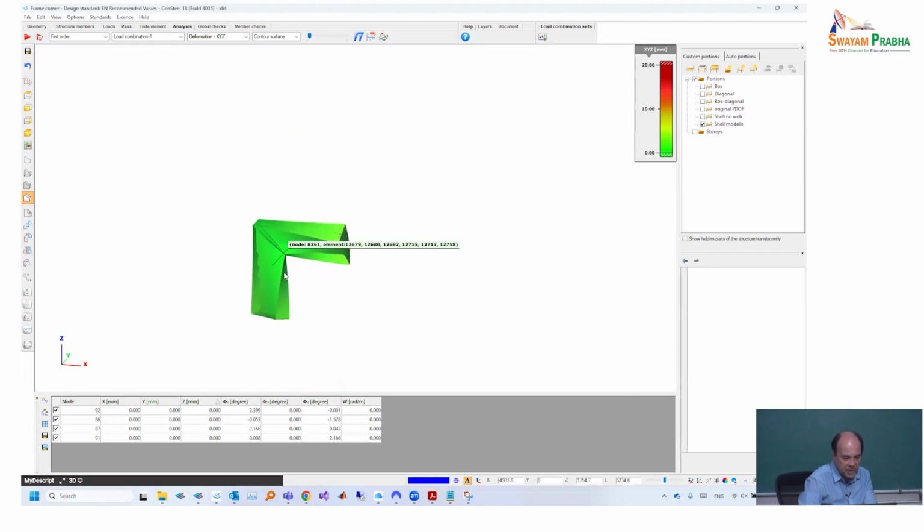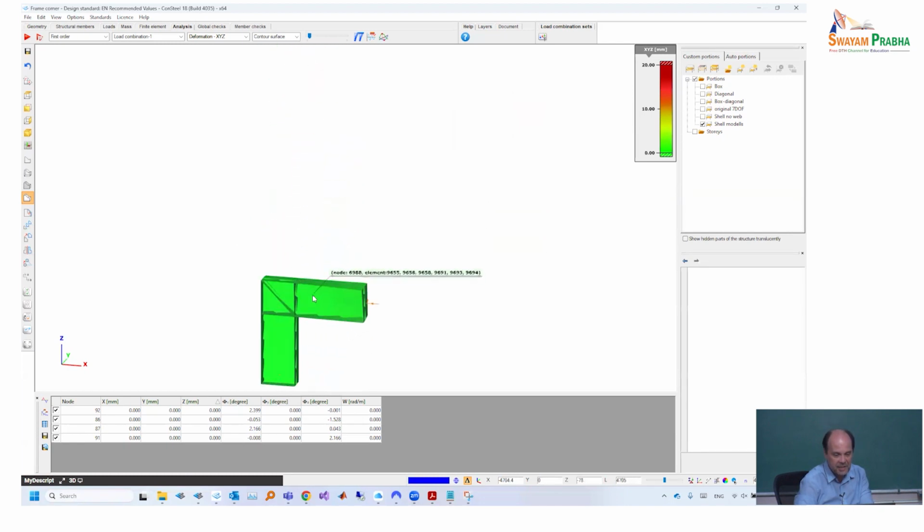So here the response is a bit more similar to beam behavior because I stopped the serious deformation of the section by placing a strong stiffener in this turning cross-section, and that's the reason that this deformation is more similar to what the beam element by itself would try to do without any information about the connection. And this is extremely important.